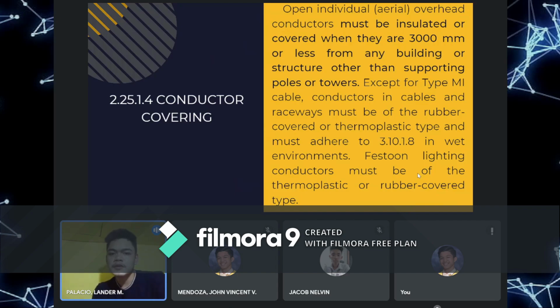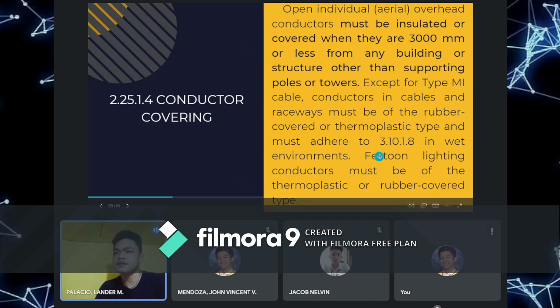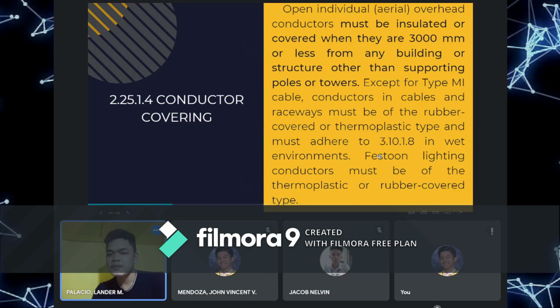So dito, yung mga overhead conductor shall be insulated daw or naka-covered when they are 3,000 millimeters or less from any building or structure other than supporting poles or towers. So there's an exception. It says here that yung type na MI cable, yung mga conductors daw sa ganong klaseng kable at sa mga raceway must be rubber-covered or thermoplastic type.